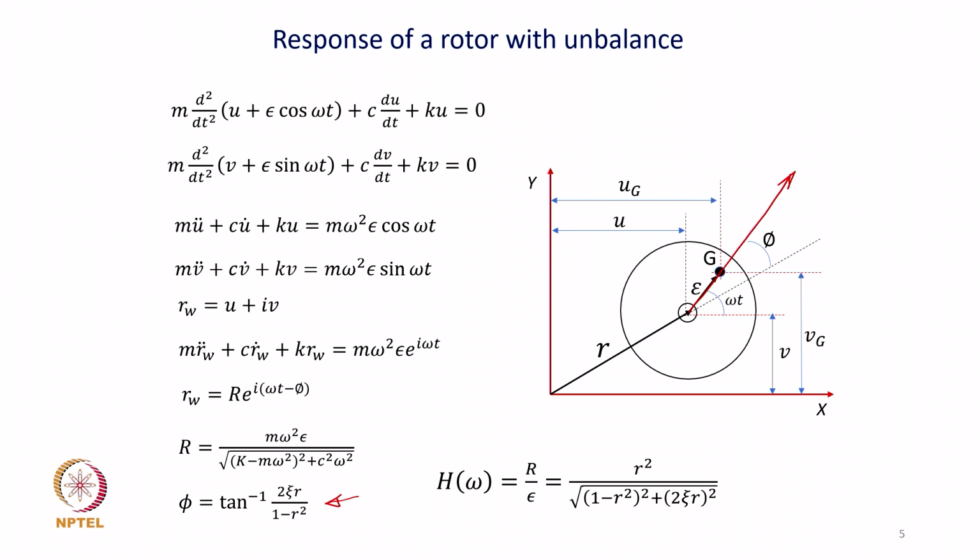Okay. What is the response? That response vector is what? With respect to the bearing axis, this is our rotor vibration response, because it is the shaft that is whirling. So, the shaft center position is where we get the response, and obviously the response lags the force by an angle phi. The force will reach its peak value first, and the response will follow. That is what we have here as details of a rotor vibration case. Phi is the phase with which the response lags the excitation force.